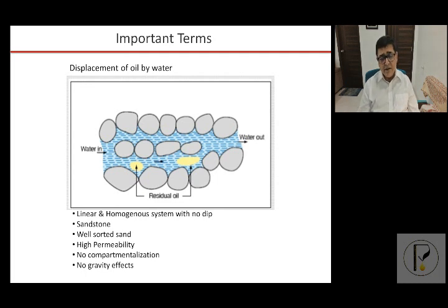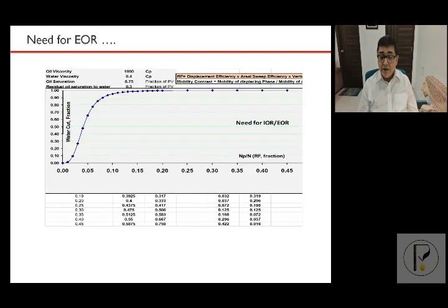Relative permeability, a very important term which we will be encountering in the fractional flow, is a dimensionless number. You can see from the y-axis the relative permeability to oil and water, and the endpoints. The SWI is the blue, increasing saturation of water, and on the reverse is the increasing oil saturation.